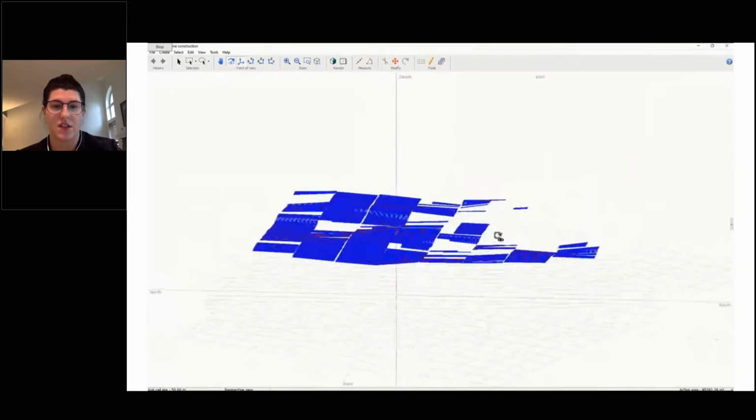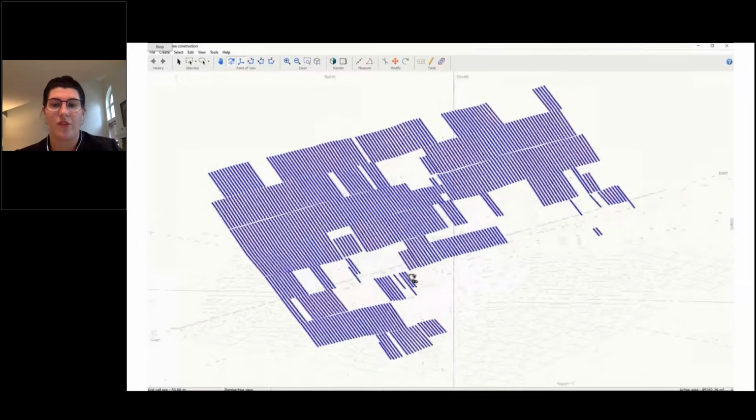If you really wanted to consider a fully accurate project in PVSyst, you'd have to create a unique table for every single tracker, which just is not possible for large-scale utility projects. So because we're able to provide this 3D shade scene, it is the maximum amount of accuracy you can assess these projects in PVSyst with, and it's much faster because we're able to import that information automatically for you.